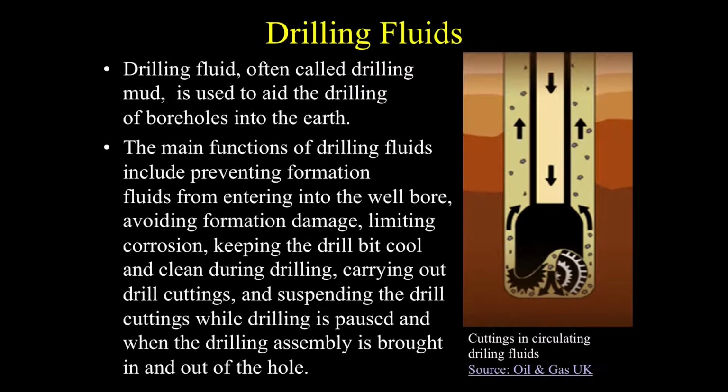The viscosity of the drilling fluid increases when movement decreases, allowing the fluid to have a liquid consistency when drilling is occurring, and then turn into a more solid substance when drilling has stopped. Cuttings are then suspended in the well until the drill is again inserted. This gel-like substance then transforms again into a liquid when drilling starts back up.